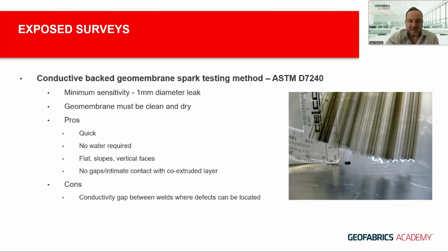So yeah, benefits are there's no water required. So in remote locations, you don't have to bring water in. And the other thing is that you can perform this on flat and sloped constructions, but also vertical faces as well. You're not losing any water. Water has to penetrate through the defect in the wet methodologies for the survey to occur.